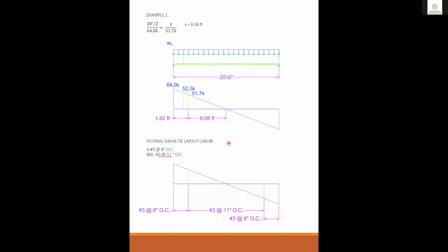So, in real life designing, is it always like there's two tiers for spacing? Usually it's two. Many cases I'll do three if they're longer spans. If it's a 20 to 30 foot long beam, generally it'd be two tiers. But if we're talking a 45 to 60 foot long beam or a double T, I probably would go to three layers, three tiers.